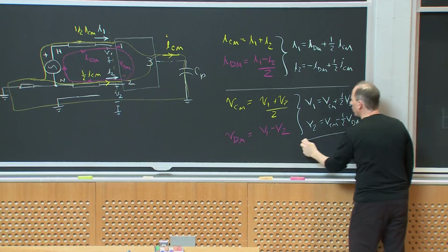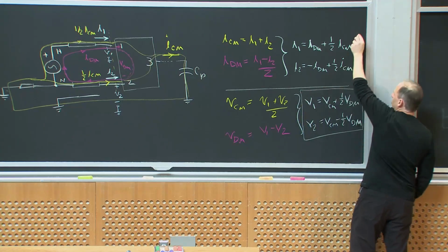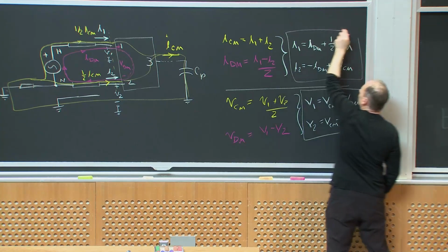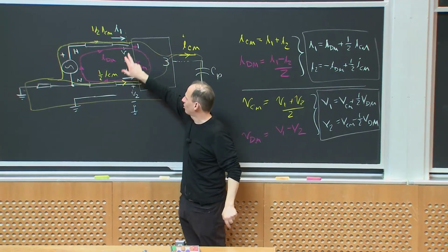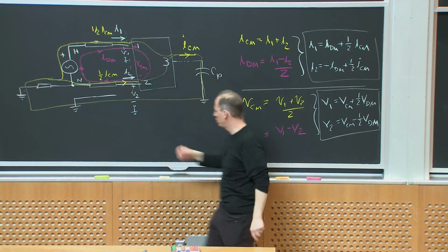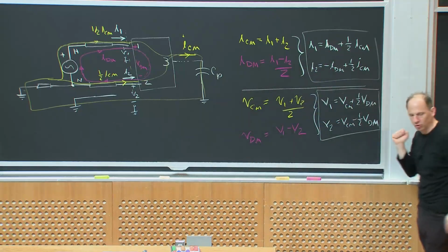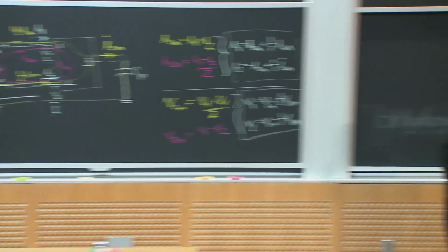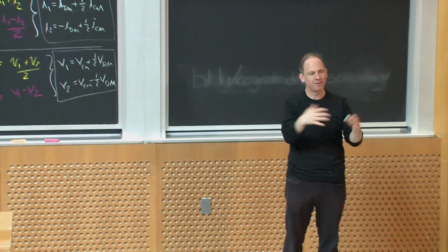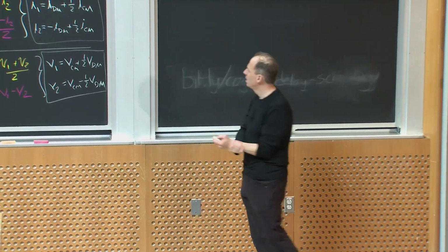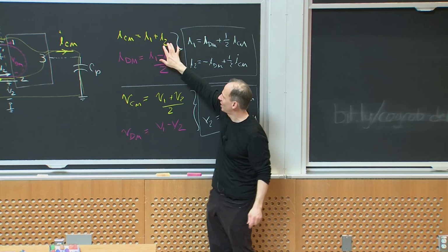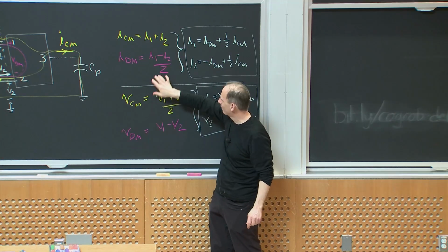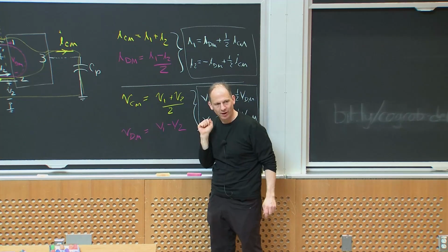Okay? So I'm issuing a decomposition of voltage 1 and voltage 2 with respect to ground and current 1, current 2 into common mode and differential mode components. Okay? So this is just a decomposition. By the way, it's kind of funny because you notice that ICM is I1 plus I2 and then VCM is the average, and the differential mode is defined the other way around.